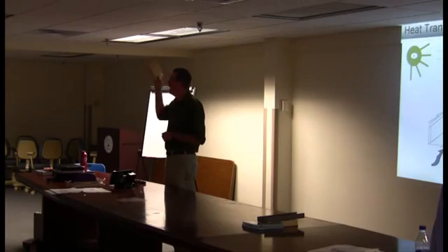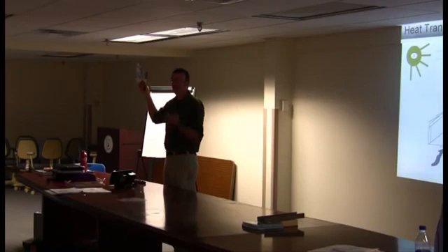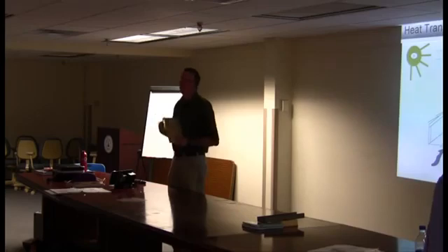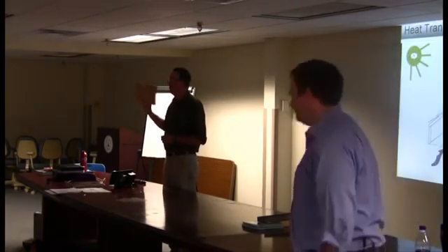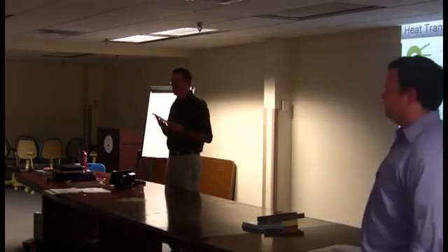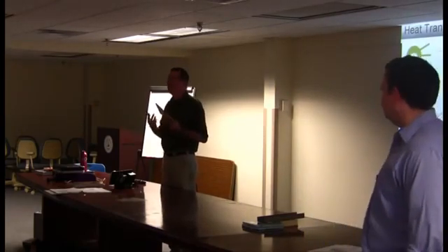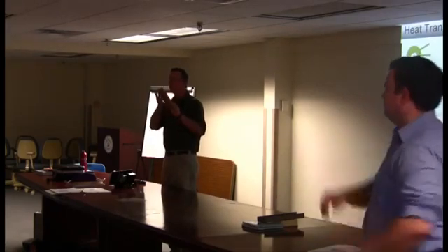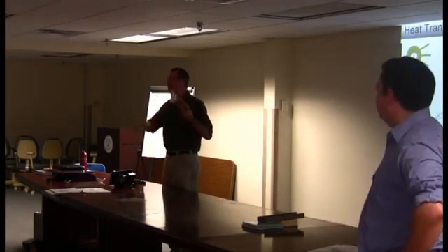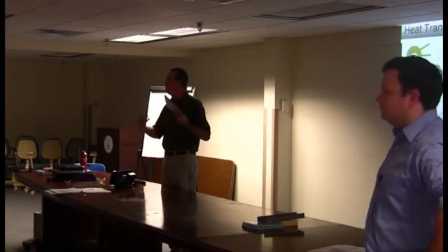Anybody been in a building that has this installed in it before? Did it work? Yeah, it's still hot, but it works. I mean, it'll probably knock about 20 degrees off the attic air temperature. Maybe a little more. But I think it actually does work. And the idea about this product, it's called a low emitting surface, because while it does get hot, if it looks like this, it gets very hot. It doesn't give off its heat very easily. So it's a low emitting surface.